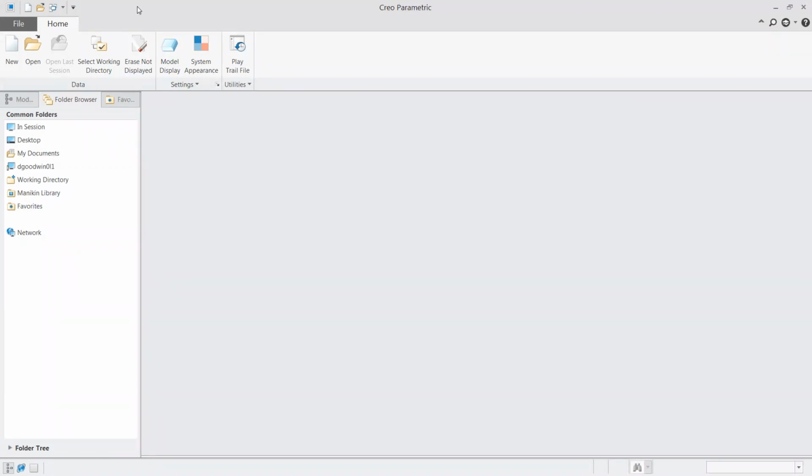What we were going through and doing there gives you free reign to reference whatever you want or build out whatever you want in that case, right? So you could put in any different characteristic, any type of reference or geometric reference. But one thing that the GD&T Advisor does, which I'll go through here and show in a moment, is it essentially doesn't allow you to put in any characteristics that wouldn't be valid for those cases, right? So it's really making sure that anything that you're laying out is going to be fully validated and it's not really going to let you make those types of mistakes.